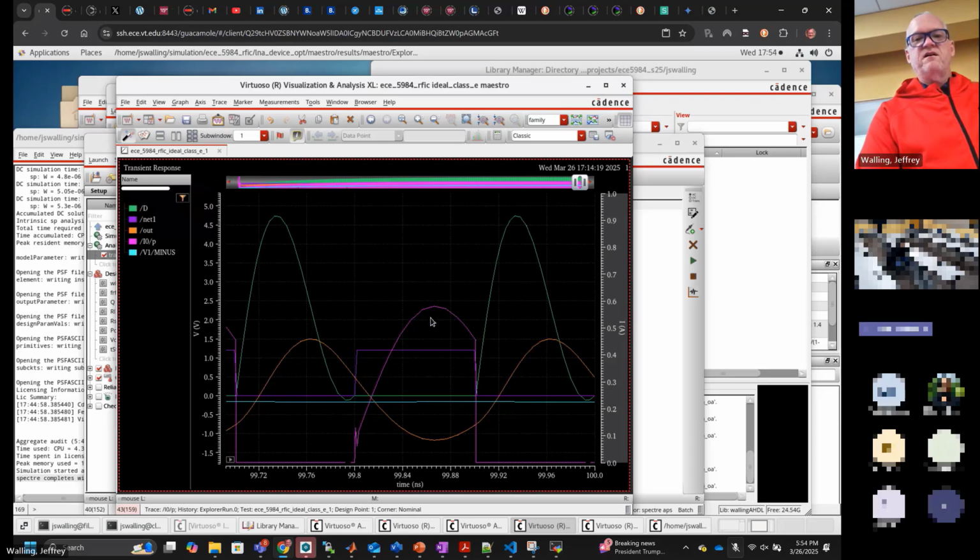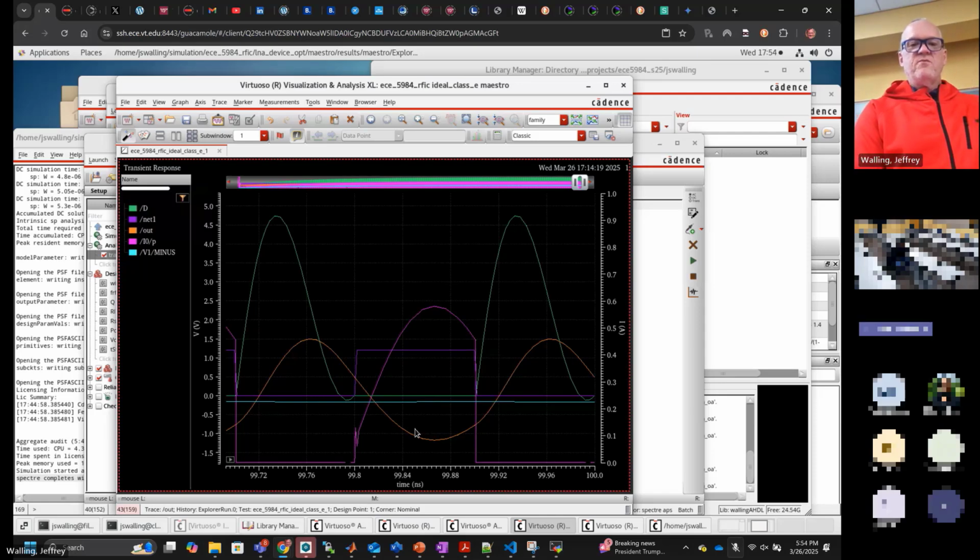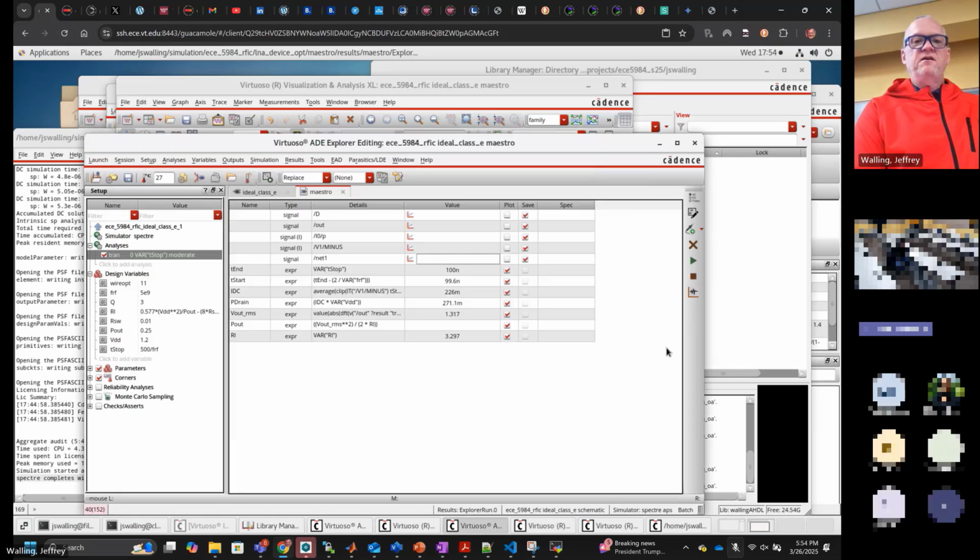but in reality, it'll start to discharge through the capacitor a little bit. So this is a class E waveform. If you go to the paper, you'll see a waveform that looks like that. And the output waveform here looks like a sinusoid. It's kind of distorted, but it looks like a sinusoid. So pretty good. You can see the voltage waveform, the current waveform. They don't overlap very much, so it should be pretty efficient. It does look like a class E.